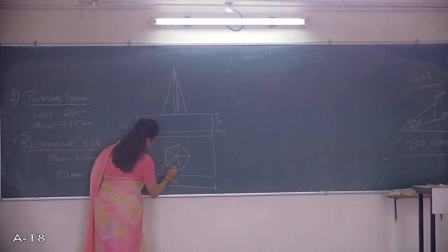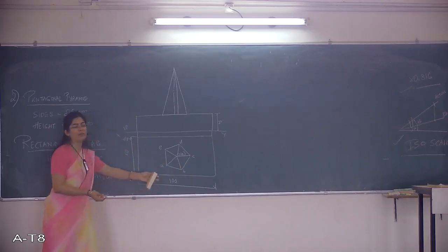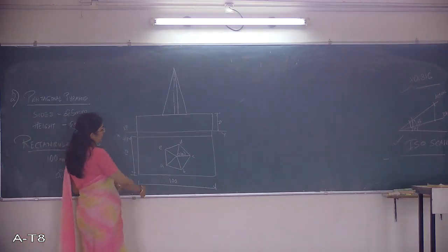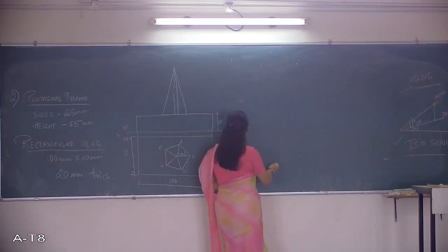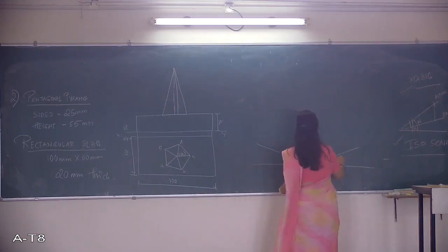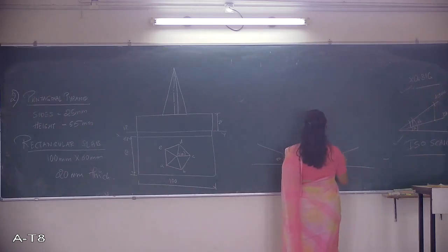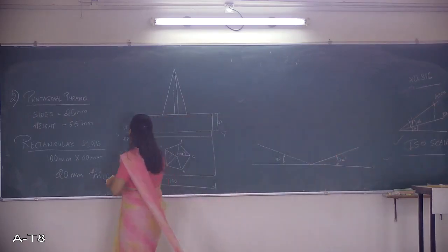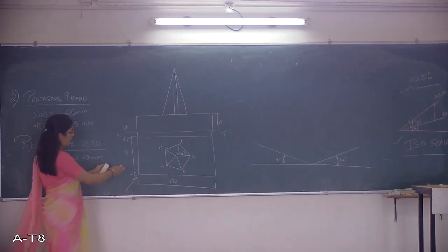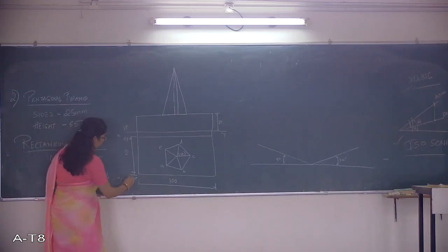Next, again I will label this as A, B, C, D and E, with this as O01. And then this is the rectangle. I would have labeled it as A, B, C, D, but not required, because we will directly start with the solution here. If you want, you can mark it, no doubt. Again, take this point and draw 30 degrees and 30 degrees, which is the procedure to get the isometric projection. After this, as I said, I am going to observe for isometric projection. You either observe from this end or this end. So I am observing from here. So this will be my point 1.